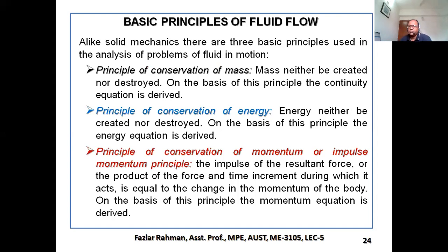What is fluid mechanics? We will apply some laws of engineering mechanics to the fluid, right? So in engineering mechanics, you will have three laws, right? Like the principle of conservation of mass, that you cannot create or destroy mass. This is one principle, and we'll use this principle and derive an equation based on it. That equation is called the continuity equation.